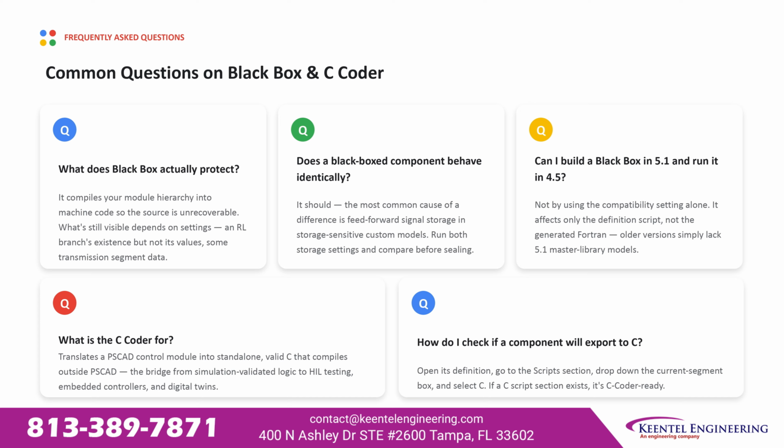How do you check if a component will export to C? Open its definition, go to the script section, drop down the current segment selector, and choose C. If a C script section appears, the component is C coder ready.